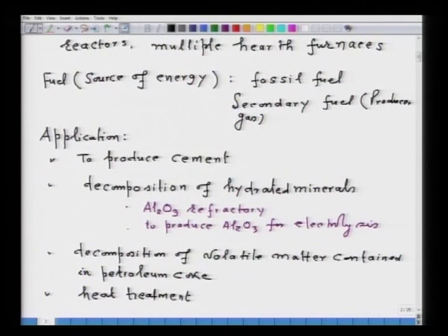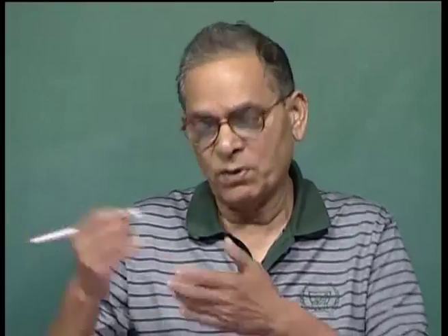However, in a strict sense you do not call it calcination, but since you are applying the heat below the melting point of the material, well, you may class it as calcination, as a heat treatment, and you may not class it, that does not matter, but all that you require is a solid state transformation from room temperature to another temperature. And so, these are the certain applications of calcination.